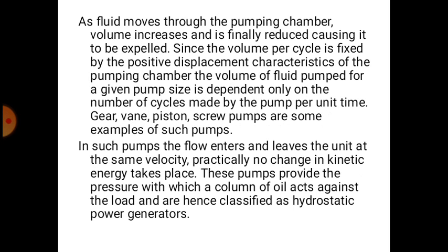A fluid moves through a pumping chamber, volume increases and is finally reduced, causing it to be expelled. Since the volume per cycle is fixed by the positive displacement characteristics of the pump chamber, the volume of the fluid pumped for a given pump size is dependent only on the number of cycles. In such pumps, the flow enters and leaves the unit at the same velocity. Practically no change in kinetic energy takes place. These pumps provide the pressure with which a column of the oil acts against the load and are hence classified as hydrostatic power generators.